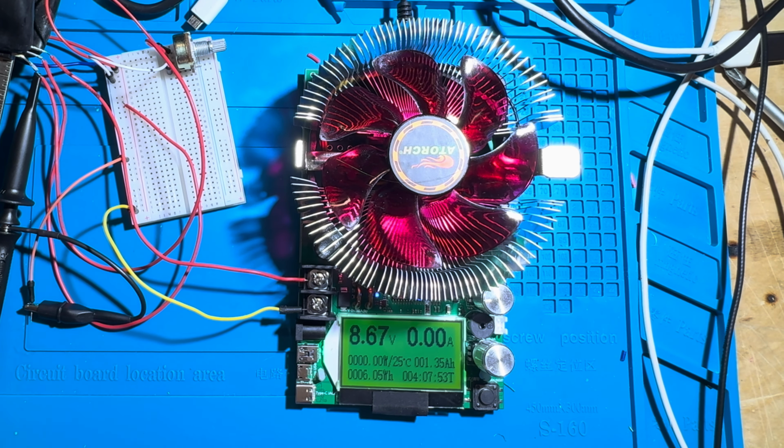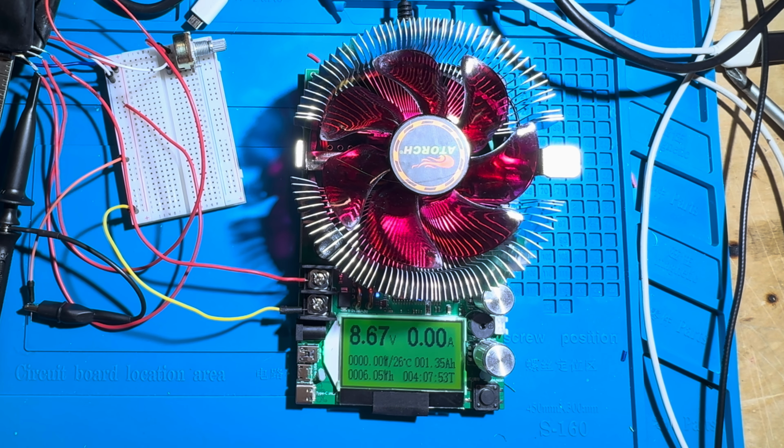So we can only get the gate voltage up to the drain to source voltage, and that's not going to get this MOSFET into its fully conducting regime, but we don't really need it to do that because we really want it to be a variable resistor. We don't want it to be full on, and we don't want it to be full off. So that doesn't really matter for our purposes here.